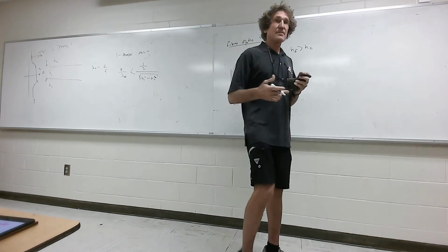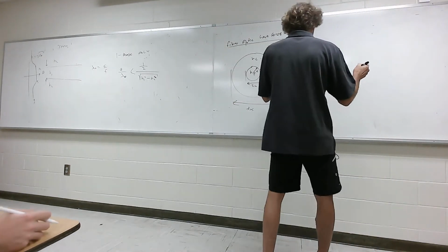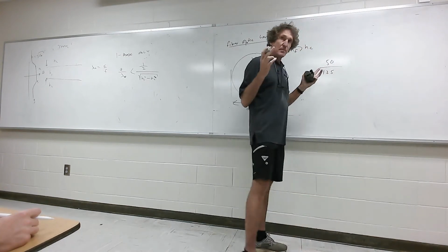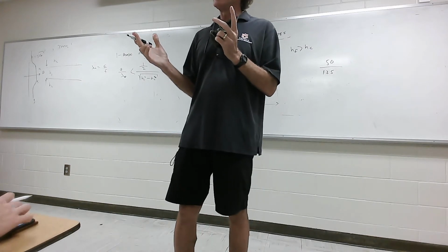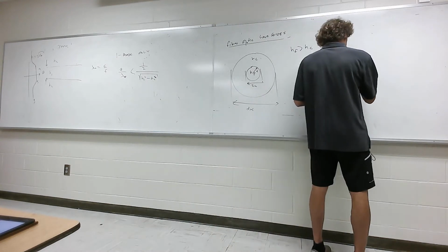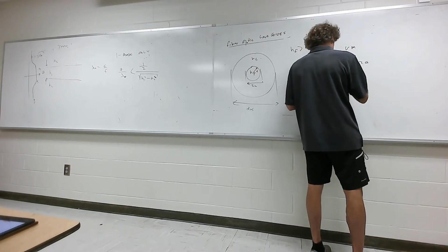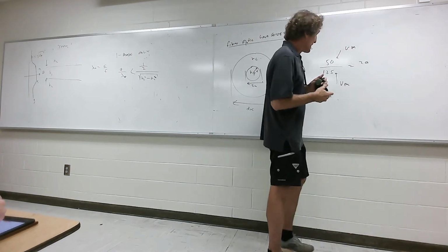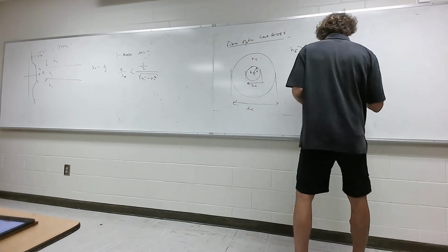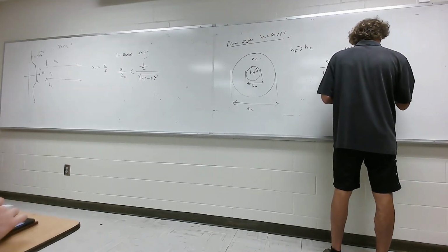So when they designate fiber optic cabling, it's typically done this way. You'll see something like 50, 125 fiber. It'll be a designation. The 50 is actually the diameter of that. This is really equal to 2A, and this is 50 micrometers. They don't put it on here. This is microns. They don't ever show this, but 50 microns would be 2A, and the 125 would be this diameter, the diameter of the cladding.